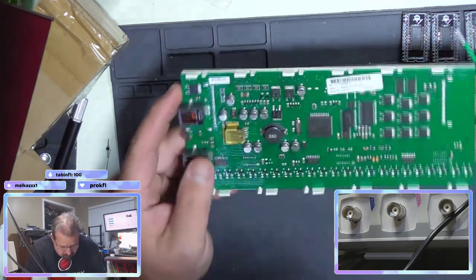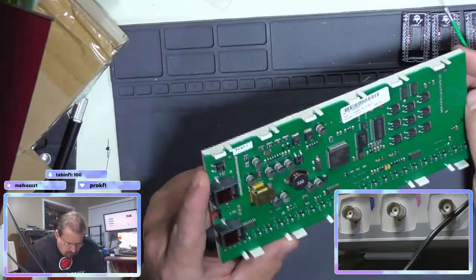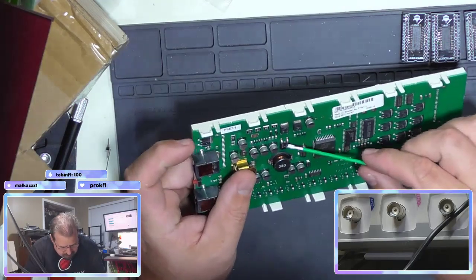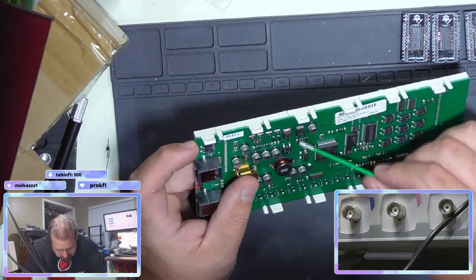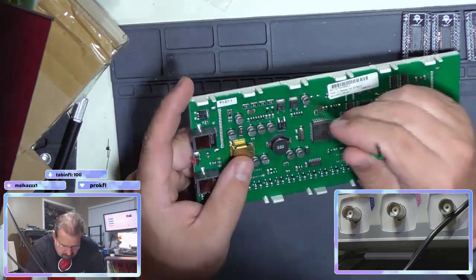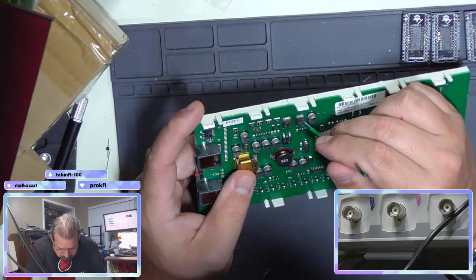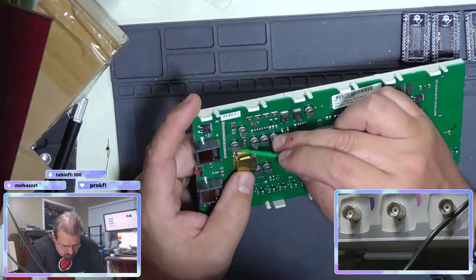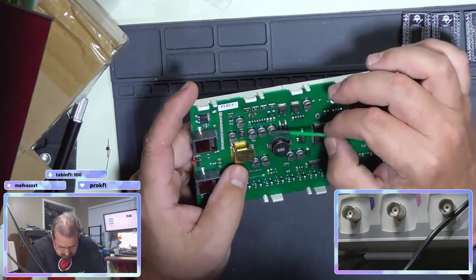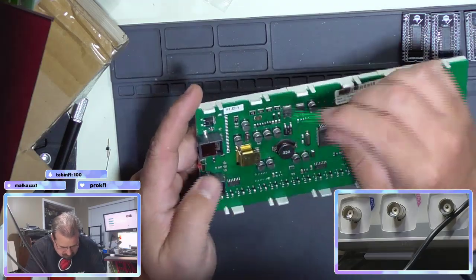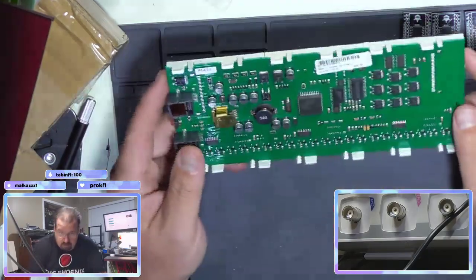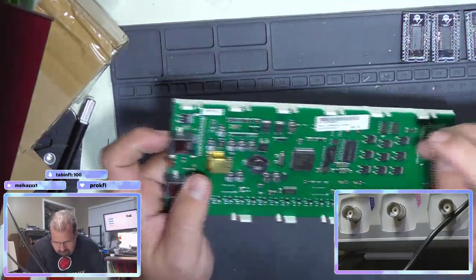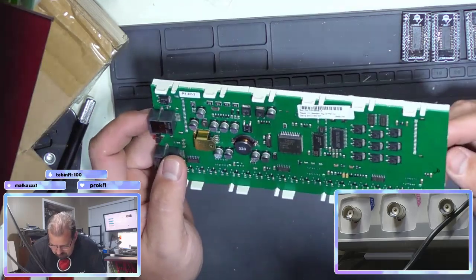We have an ON Semiconductor up here. There's some kind of regulator right here. Buck boost transformer. These two transistors are the same, 64OTGs. 7805. So here we go, we have a 7805 regulator. So this most likely takes a higher voltage and then down converts it. And then it's daisy chained as well. So it probably runs on like a 24 volt loop because these all get daisy chained. Obviously, there's a serial EEPROM here to control the address of the display. Each display is addressed.